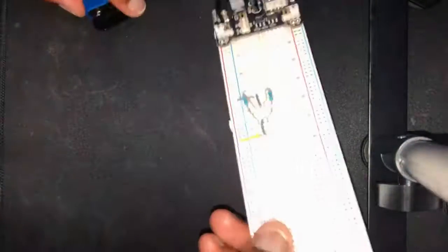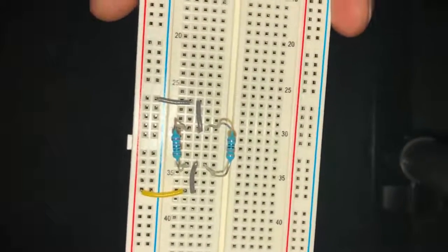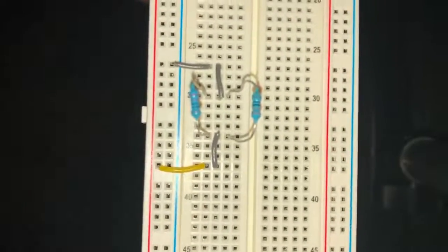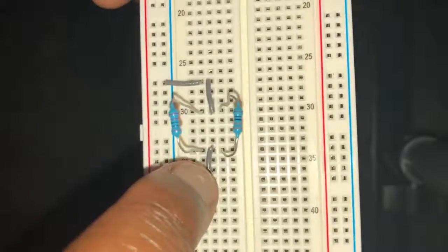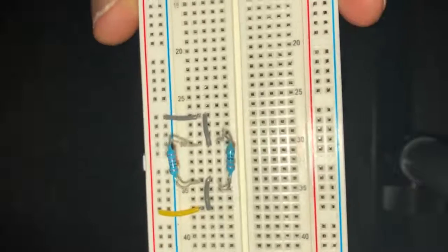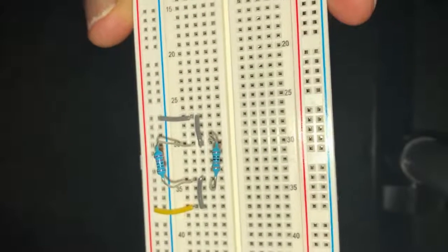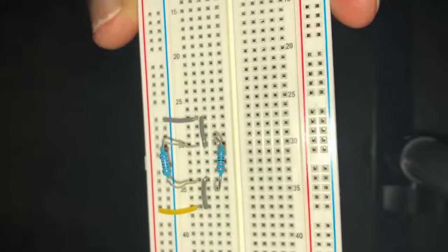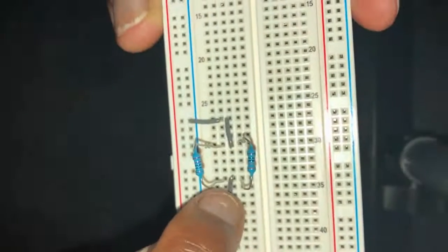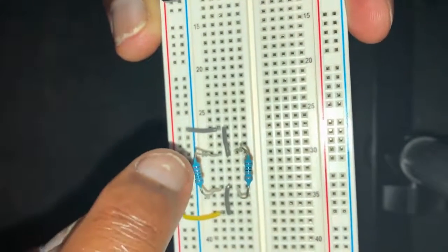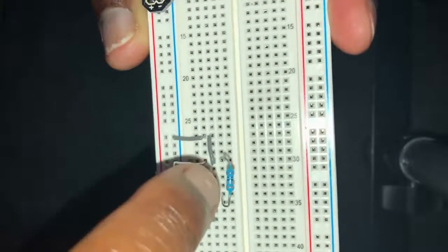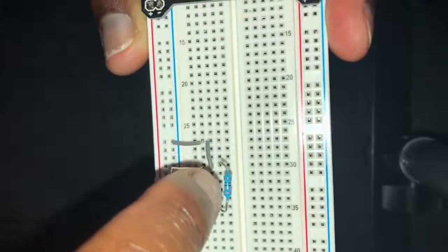So let's make a circuit and see how this actually looks with a real circuit. So the next circuit basically has the 220 ohm resistor and 330 ohm resistor in parallel with each other. So I've got power coming in on this side, and I've used 2 extra small solderless wires to recreate the parallel circuit more like what we drew earlier on. So the current splits off at the junction there. Some current goes into there, some of it goes into there, depending on their resistances. And the current then comes back together at that junction and then goes to ground.